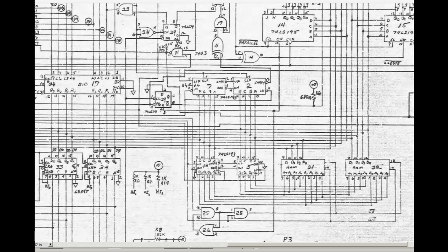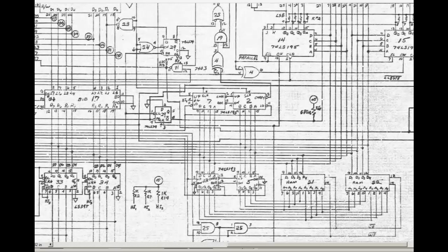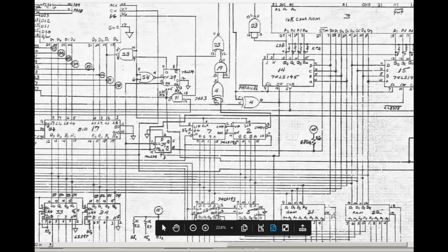As I'm going to demonstrate and explain in this video, the data from the RAM also can go directly to these shift registers, in which case it's not inverted. So whether the data stored in the RAM is inverted or not inverted depends on where it comes from and where it's going. And of course, if the nano processor reads the data back out of the RAM, it is inverted, and so we need to be mindful of that when we are looking at the data.